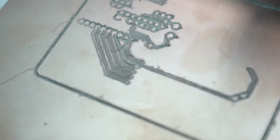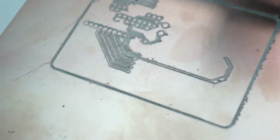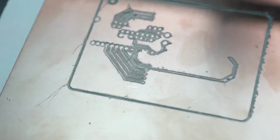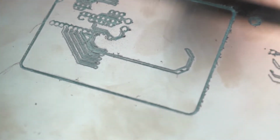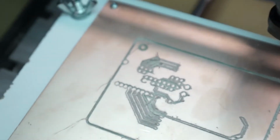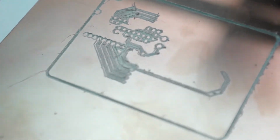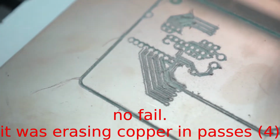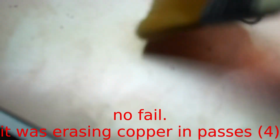All right, full disclosure, that's my first fail. Multiple fails there. First of all, I forgot the height map, which I carefully made and then didn't apply, because there's a little thing you have to click. Secondly, somewhere in the middle, the CNC machine just stopped, so I restarted it, and then it went over its own tracks, but it erased them. So yeah, that's a definite fail. Not to mention the third fail, which is that this one was in a mirror image.